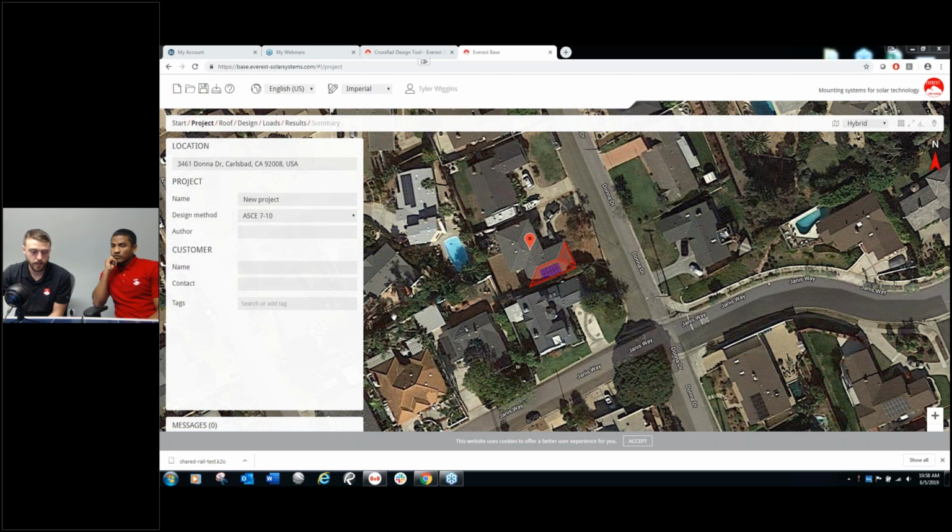For example, if you are in Mexico City, the building code you might use is that particular building code for Mexico City, and those wind loads might be different than the building codes required in Cabo San Lucas, since there are going to be hurricanes there. So really, what we mean by ASCE 7-10 is the particular building code that is used, at least right now in Southern California, with that particular wind speed.